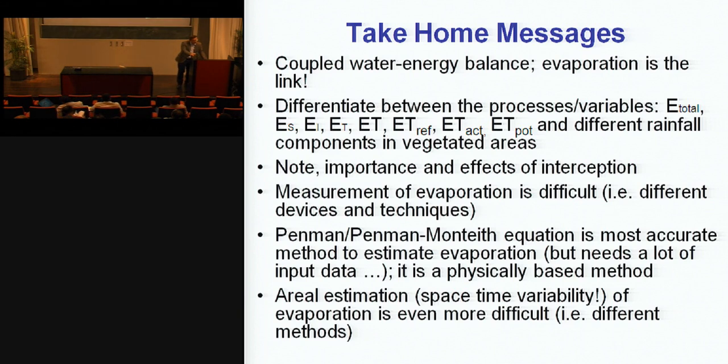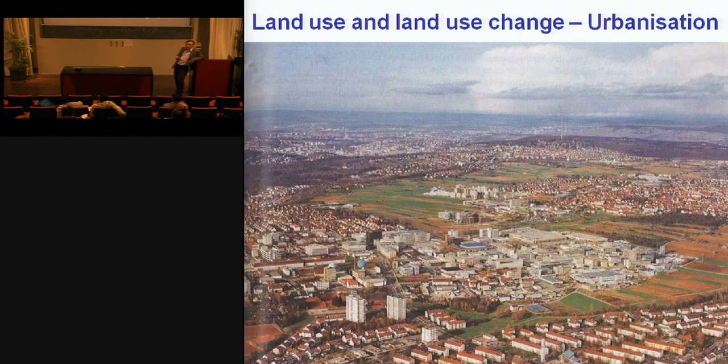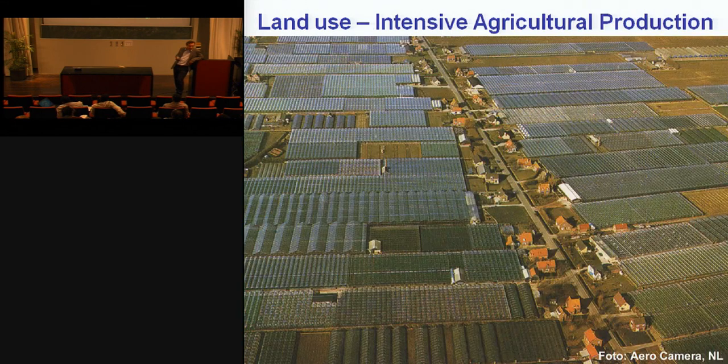Yes. So what happens? Rainfall is falling here on the glass roof. What is happening to this water? It's not going down. It does not meet any plants directly. It flows on the glass and goes to a drainage system. Some of the water is then stored and used for irrigation in the greenhouses. And most of the water is discharged away. They only store the water that they need for watering the plants. But there's no infiltration to the ground, no groundwater recharge in this situation. Therefore, it's discharged directly and brought to a drainage canal and often to the next river.